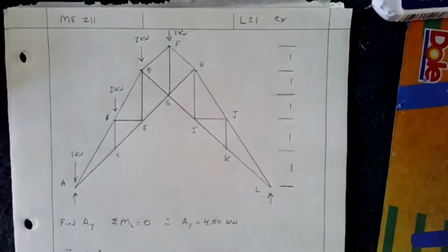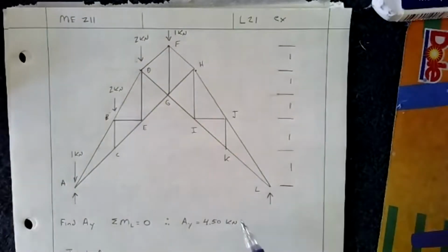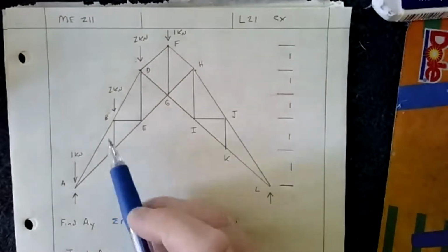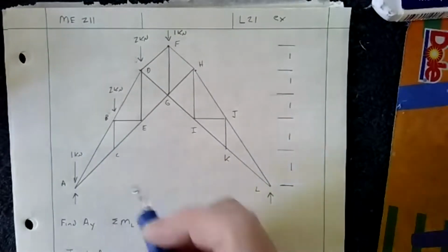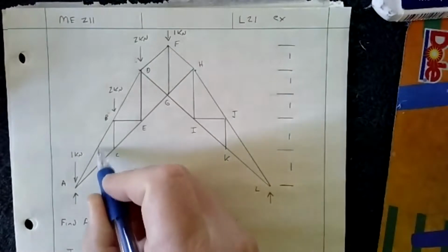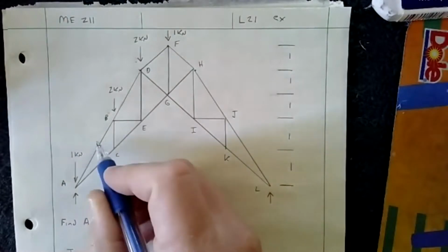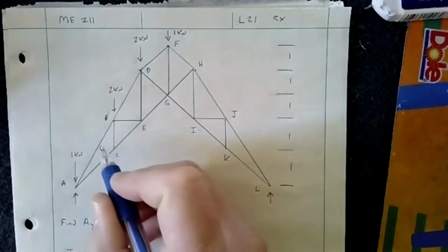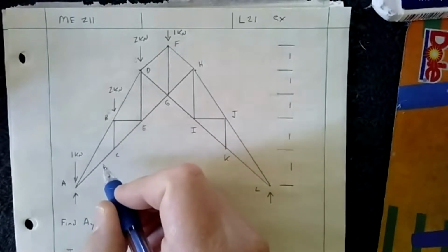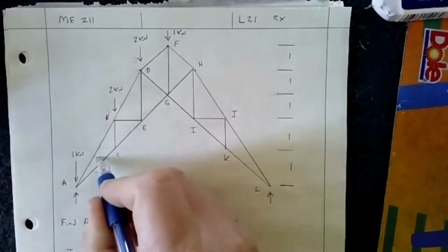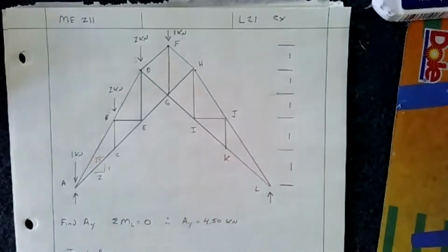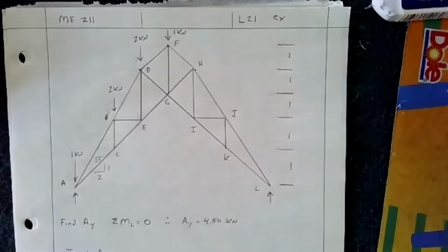So here's my truss. It's an exaggerated way I've drawn it. But one of the things to notice with these arms, especially if you look back at the drawing, is that this here is a 45-degree angle because it rises 2 and goes over 2. So that's a right triangle. And this is a little different. It's going to rise 1 and run 2, so it's over root 5. We're going to use that in our calculations.